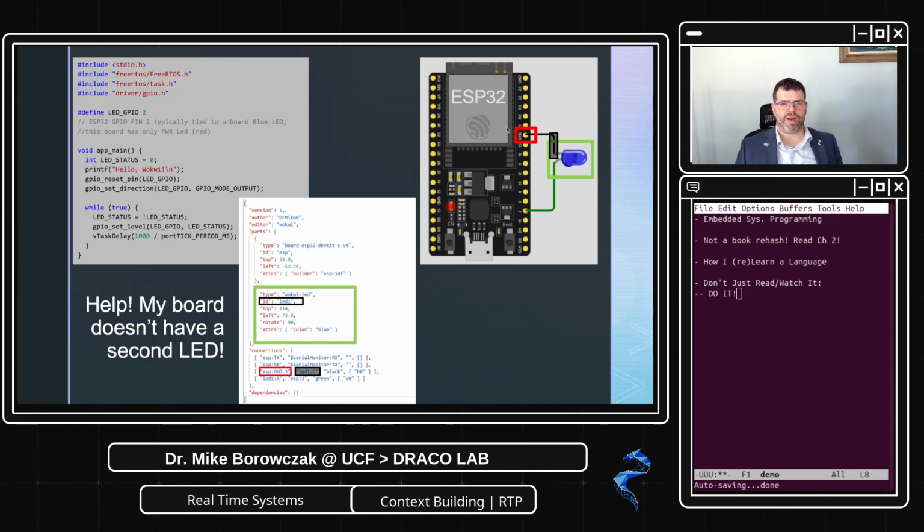Now there are actually 3 or 4 grounds on this ESP for sure. There's 1, there's 2 at the top, there should be 1 here on the left-hand side, so 3 grounds, probably labeled 1, 2, and 3. So ESP ground 3. See what happens if you modify the diagram.json file, modify that to a 2 or a 1, and see which one it connects to. The Wokwi interface should allow it to reroute it. Maybe not nicely, but it will reroute it. Okay, so we continue on.